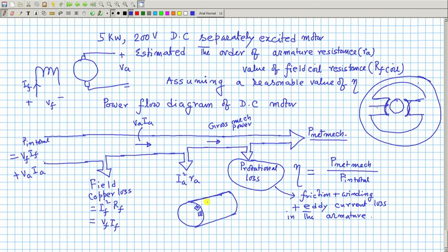Therefore, in the iron body, pick any closed path: it will sometimes see maximum flux linked, sometimes zero flux. There will therefore be an induced voltage by Faraday's law, an AC voltage, since there is no commutator and rectifier here. So there will be eddy current paths available in the iron body, and the iron will also become hot.